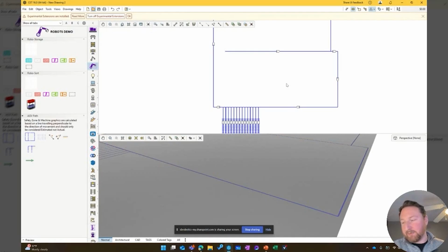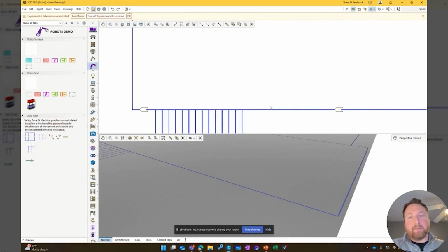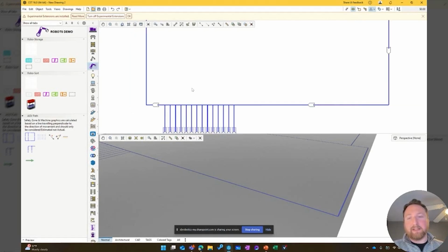There's going to be some limitations with that. Like I mentioned, the verticality is missing. You can't really use it for AGVs that, for instance, don't have a turn radius, don't have a differential drive, and maybe turn on a zero-point turn, or confined axis there. The pathing isn't the most detailed as well, and oftentimes those curves, for instance, have less direct turning. They'll require extra clearance for that vehicle swing as it moves through.